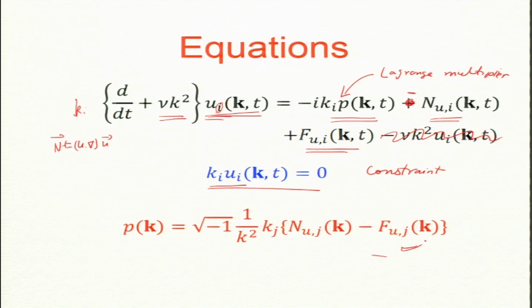Okay. So, this pressure, we have done it before, but you must remember that sometimes you should not ignore the force. The force may have divergence; k_i f_i need not be 0. I put a notation for our consistency: a subscript u, which means this is the force on u. There could be force on other fields like the magnetic field, velocity field or temperature field, so then it becomes f_b or f_theta. Okay, so this is a notation. There are a few typos here. So, what is the method?